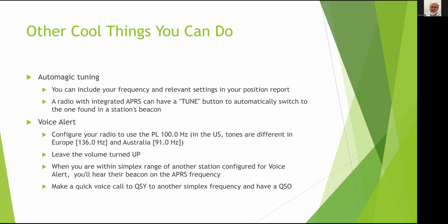Okay, because there are some TNCs that are set to be open squelch all the time. That is correct. And you will also find some devices like the Tiny Track 4 that are unidirectional. They only know how to transmit. They don't know how to receive, and they don't care. They will just transmit when their little timer expires. They'll transmit whether somebody's already transmitting or not. They don't care. So yeah, you have to take that with a grain of salt.